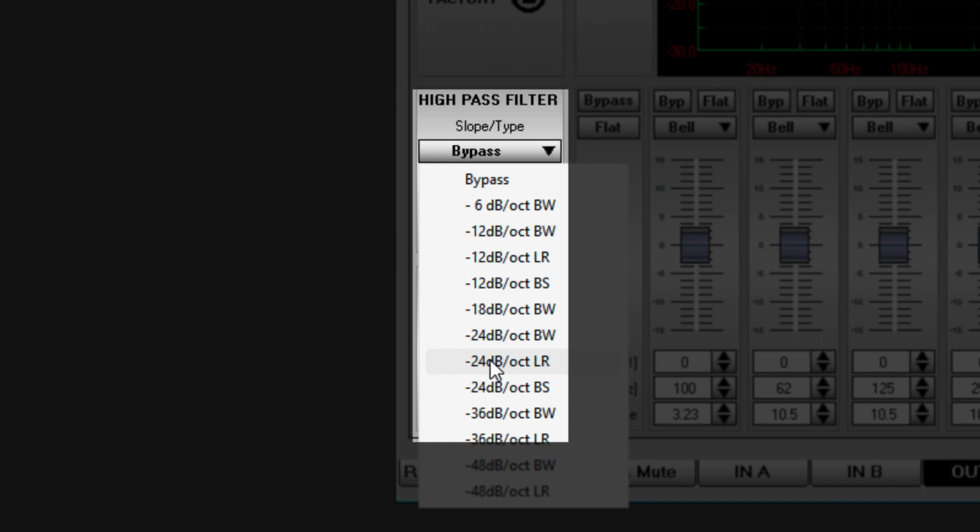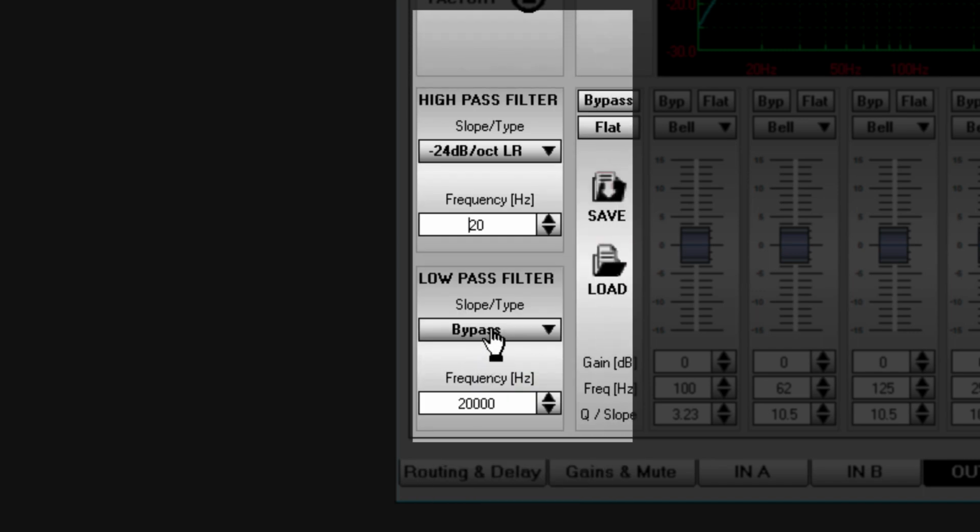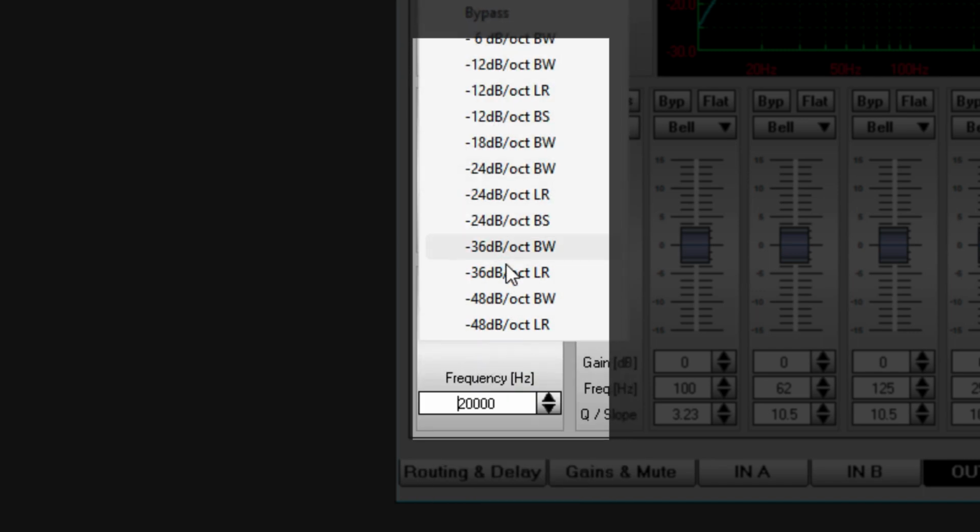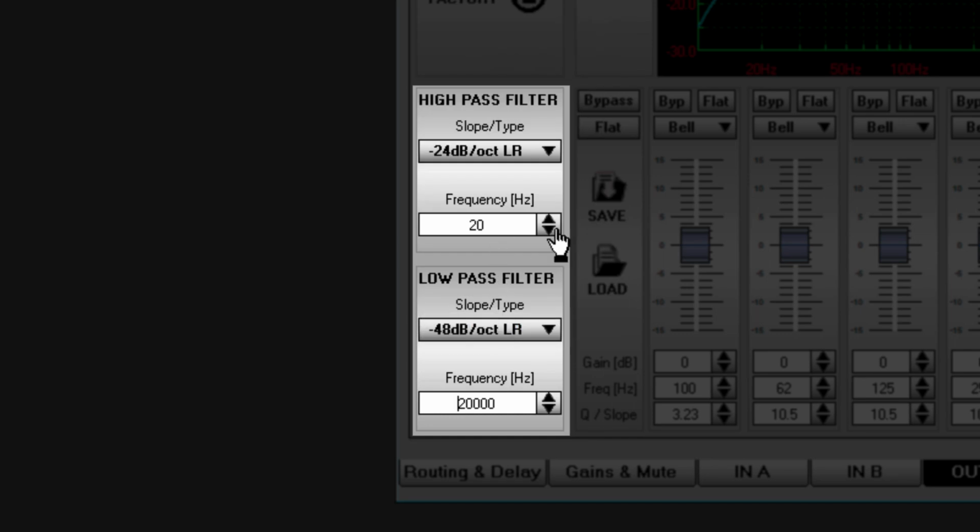The frequency can be selected either by stepping up and down in increments of 1 Hz or by directly typing the value in Hz and clicking Enter. Note that frequency is always in Hz. K is not recognized, so for example, to enter 1.2 kHz, you need to type 1200, enter.